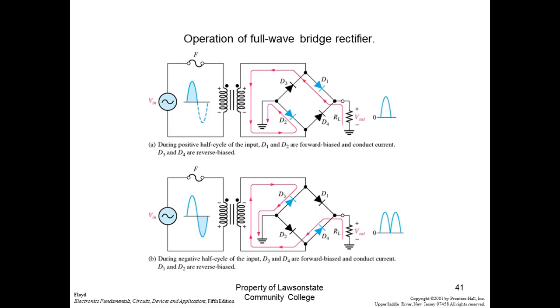Since this is drawn kind of similar to a Wheatstone bridge, it got the name bridge rectifier. We're not using a center tap transformer. You can, but you just don't use the center tap. Or you can use the center tap and have a negative and positive supply, which is pretty neat. Yes, exactly. Transformers that are not tapped are cheaper than transformers that are tapped.